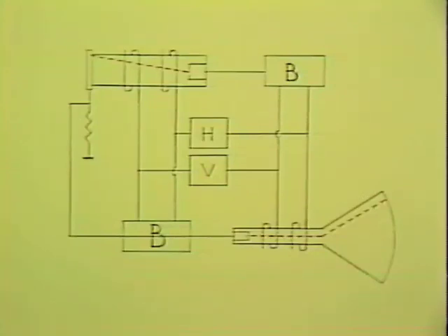In the camera, the beam is set to a constant strength, and in the picture tube, the beam strength is varied by the incoming video signal. During the active scan time, the blanking circuit does not interfere with the beam. But during the retrace time, the blanking circuit simply switches the electron gun off and no beam is produced.